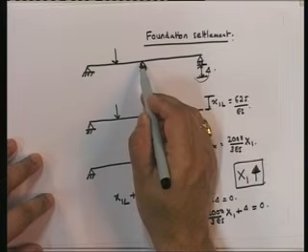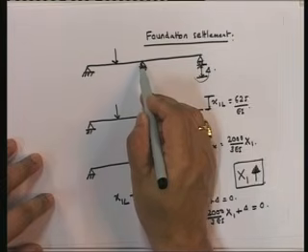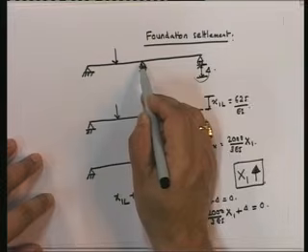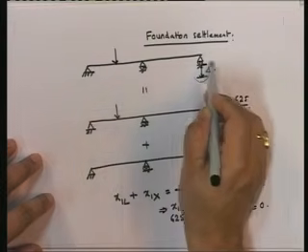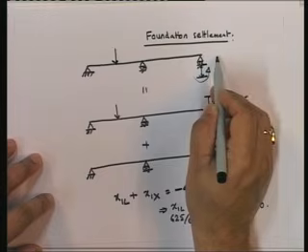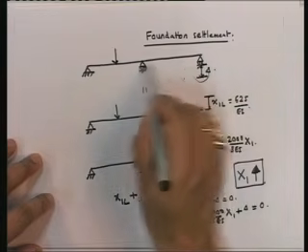I have already talked about lack of fit in trusses, and I am not going to talk about lack of fit in beams, okay, because it involves a little bit of a difference. For example, a beam being longer does not really affect the stresses in the beam. Think about it. In this particular case, if this beam, instead of being 10 meters, was 10.1 meters, what would happen? The only thing that would happen is that these rollers would just move to the right and give no forces in the member.